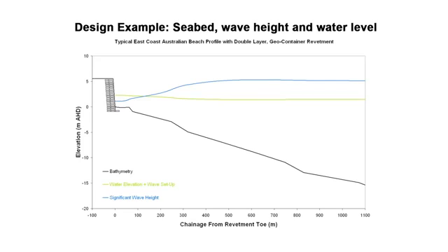So this wave rises a little bit in height in shallow water, and then it starts to feel the bottom, so it breaks. So it starts reducing in height as it comes down. And in this case, the wave height at the structure is probably 1 to 1.3 metres. So the wave height by the time it hits the structure is about 1.3, but we started with 6 metres offshore.